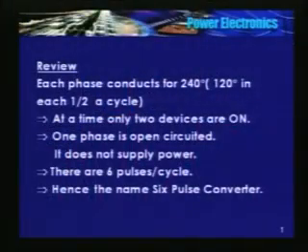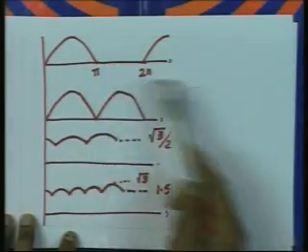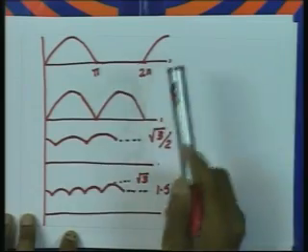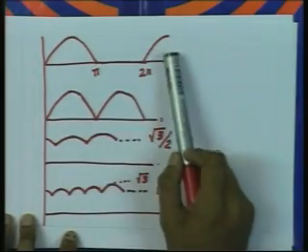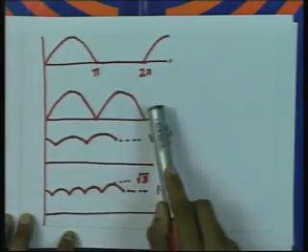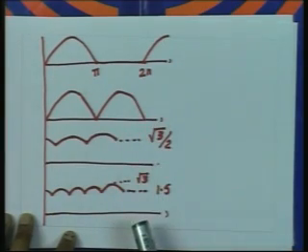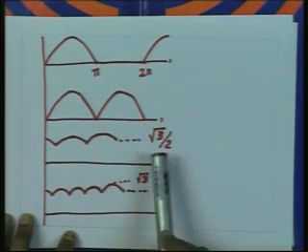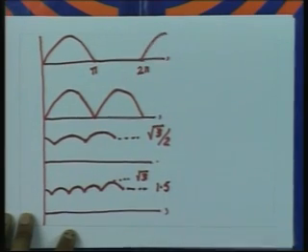So far you have studied 1 pulse, 2 pulse, 3 pulse and 6-pulse converters. What are the advantages of increasing the number of pulses? I will just show you a transparency slide. This is a waveform for half wave rectification. I am assuming either a purely resistive load or a half wave rectification using a freewheeling diode. Then the full wave rectifier, 3-pulse converter and a 6-pulse converter.